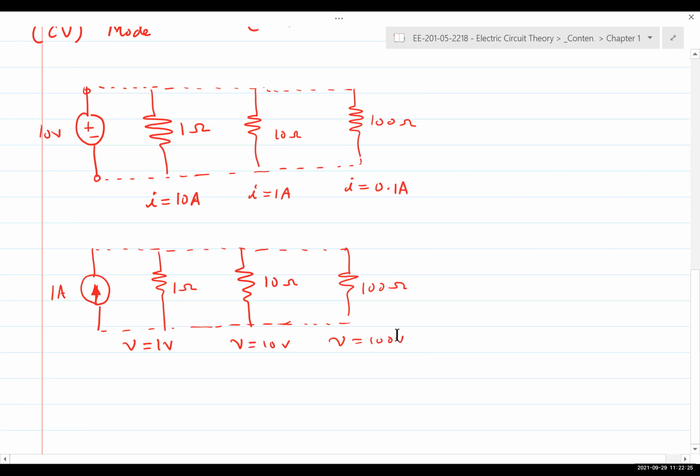It cannot go more than that. Even if I connect 10 ohms to my power supply, it can send 1 amp, no problem. If I connect 1 ohm and I want 10 volts out from it, it needs 10 amps to provide 10 volts. But if it can only supply a maximum of 3 amps, what is my voltage now?